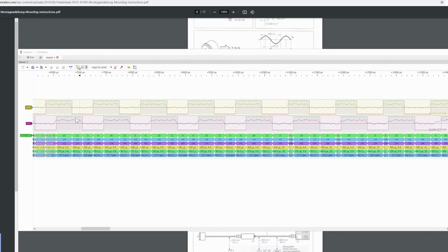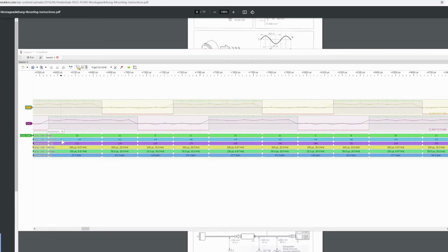And the nice thing that I'm seeing here is, again, I think the probe on my oscilloscope needs a little bit of tuning, but this looks really nicely 90 degrees out of phase, which is what you want in one of these encoder signals. Now I plugged in a thing called gray code decoder, and this is very cool because it gives you a bunch of additional information. The first line is a phase count. I'm not really even sure what that is. Then we've got increments, which I also don't know what it is.